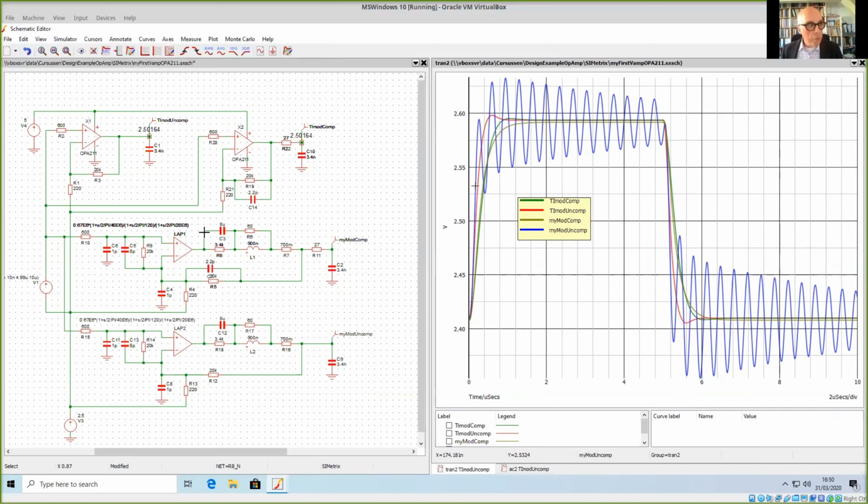So although the macro model is really very large and provided by the manufacturer, I think we learned a lot: modeling of the operational amplifier, just only the behavioral aspects that are relevant, as we did in SLiCAP from the data sheet, gives a much better result than using this macro model, and it is much faster.